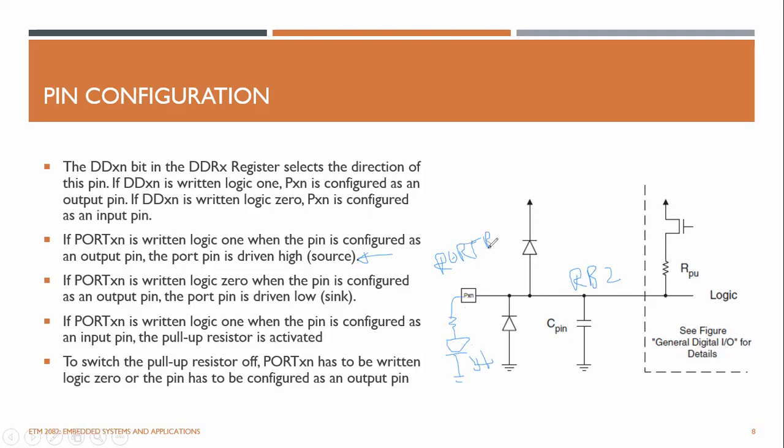Port B2, you set it as 1, so this LED will be high, right? And sinking is where you can drive the current. In that case, you can connect this to 5 volt, and this is a resistor and this is the LED. You can connect it in this configuration, right?